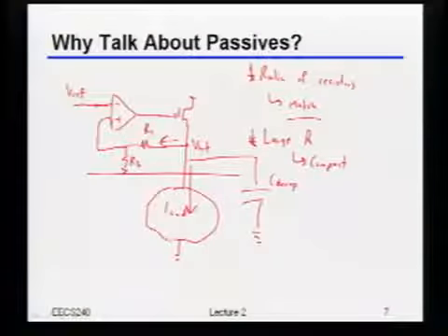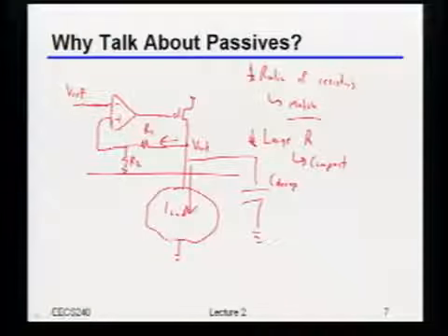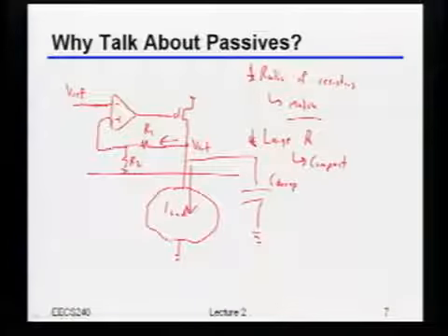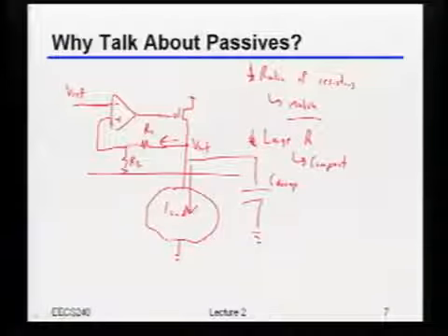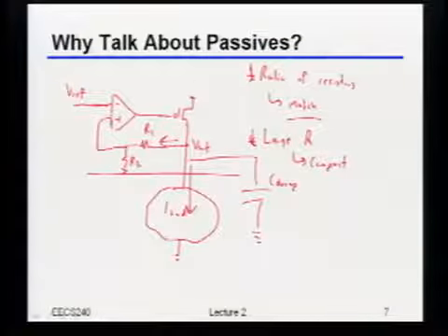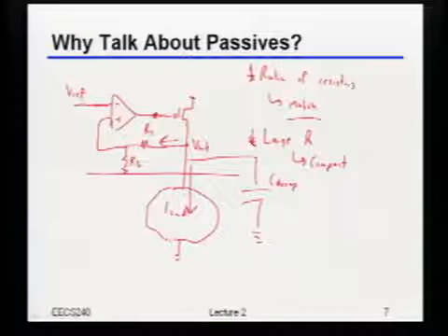Okay, great. That's actually several of the things we've talked about, so that's almost all of them. Just to clean off this example, any other passive components that you think might be important in this context? By the way, this is usually the first thing they tell you to look at when you do feedback loops. Compensation. Yeah, there we go. You want to make sure the darn thing's stable. So usually, not always, you probably want to put your dominant pole over there.